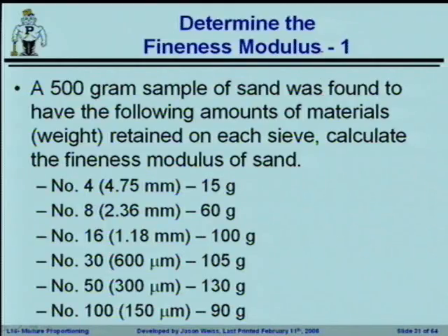Let's assume, to determine the fineness modulus, we've got a 500-gram sample of sand. It was found to have the following materials, the weights retained on each sieve. Calculate the fineness modulus of sand.